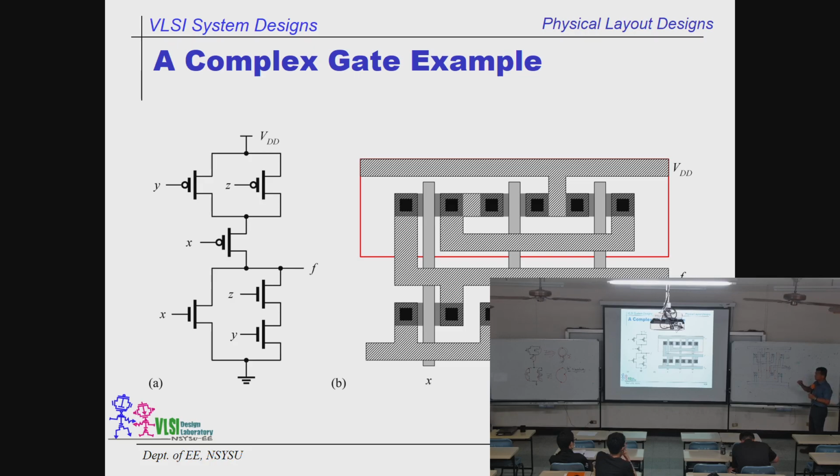Why do we do that? Because that will save you a lot of trouble. Why is it a lot of trouble? Because you don't have to worry about the sacrifice of area over here, or how to align all the signals. As long as you take some practice, you can get a very good result like this one, and it will save you a lot of trouble finding the minimum number of tracks. The fewer tracks you use, the more area you will save.